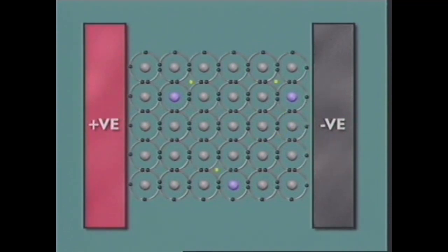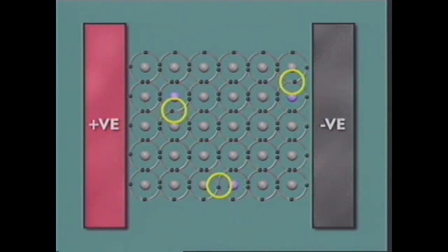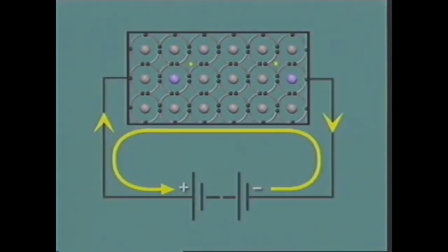The number of charge carriers in a material can be altered by doping, or adding very small quantities of impurities. A doped semiconductor always has an excess of one type of charge carrier. Electrons in excess make it an N-type semiconductor, N for negative. Holes in excess make it P-type, P for positive. When connected into a circuit, both the electrons and the holes move, and current can be thought of as moving in two directions. So electron current and conventional current are both used in electronics.